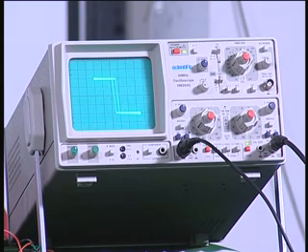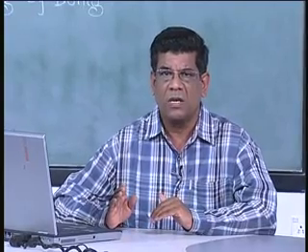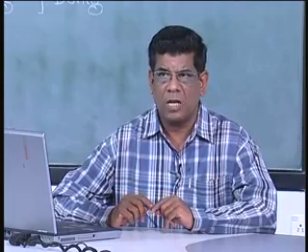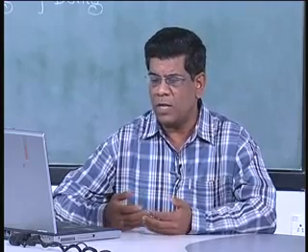So having seen the transfer characteristics of the operational amplifier using an oscilloscope, where you can see the two saturation regions corresponding to the output, and then the two transitions corresponding to the open loop gain when the two voltages are very very small. We have seen that. Now let us move on to the next characteristic, which is called the gain bandwidth product.